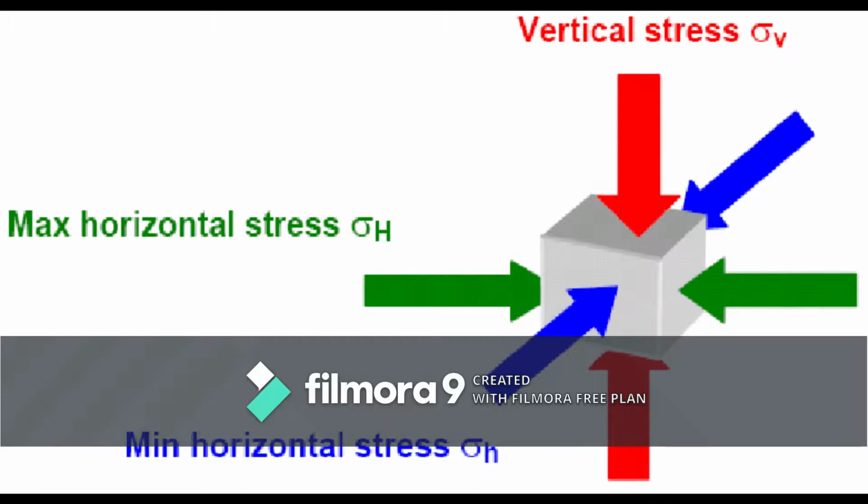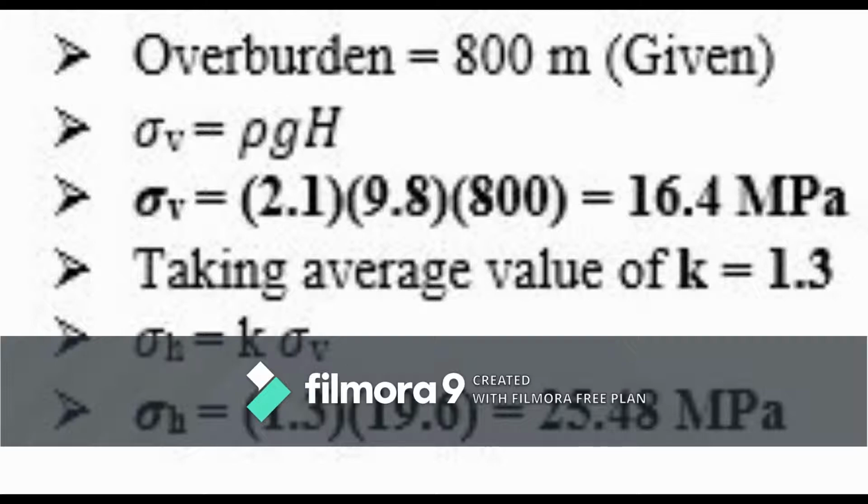In this section, we will try to calculate the in situ stresses. For this reason, we have used the analytical method, or you can say formulas, to calculate the vertical stress and the horizontal stress. The vertical stress calculated is 16.4 megapascal and the horizontal stress is 25.48 megapascal.